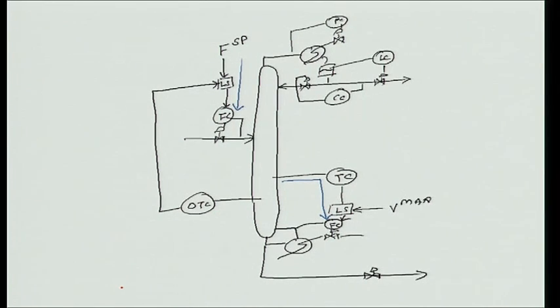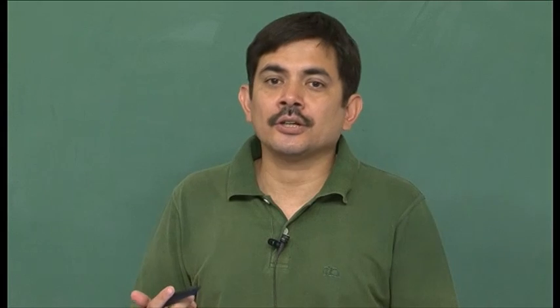Once the throughput goes high, V1 goes maximum. So, therefore, V1 is fixed and temperature is controlled this way by adjusting the feed. Do you see how these low selects actually end up altering the control structure when a constraint is hit?